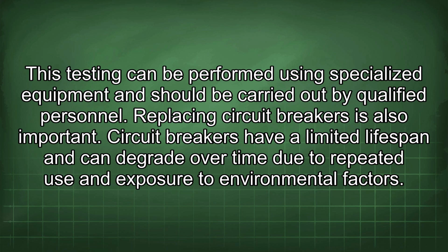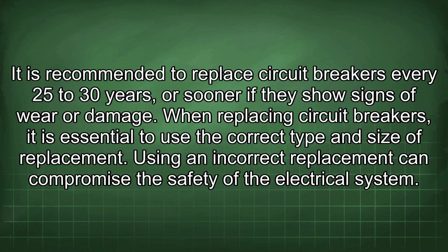Replacing circuit breakers is also important. Circuit breakers have a limited lifespan and can degrade over time due to repeated use and exposure to environmental factors. It is recommended to replace circuit breakers every 25 to 30 years, or sooner if they show signs of wear or damage. When replacing circuit breakers, it is essential to use the correct type and size of replacement. Using an incorrect replacement can compromise the safety of the electrical system.